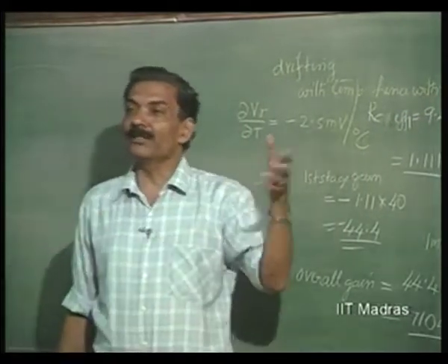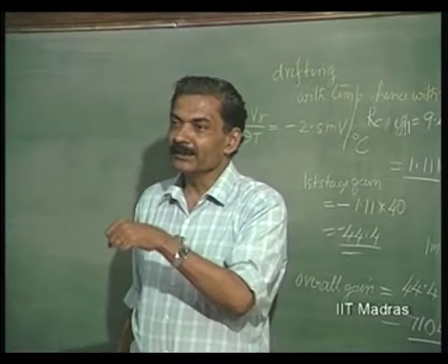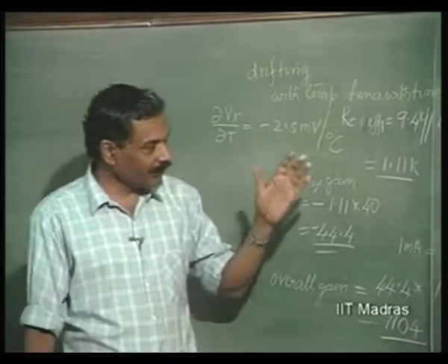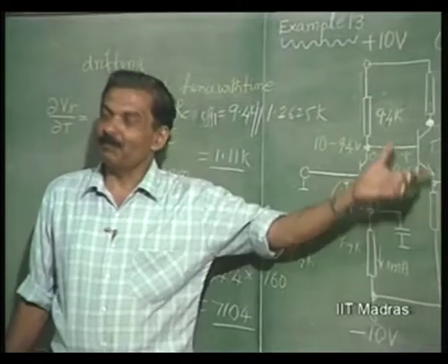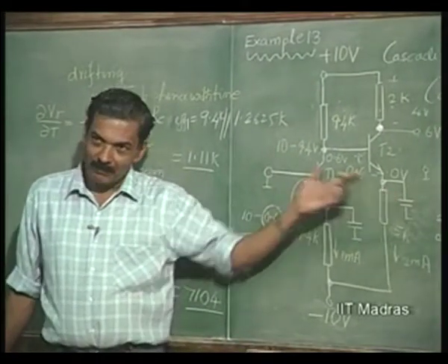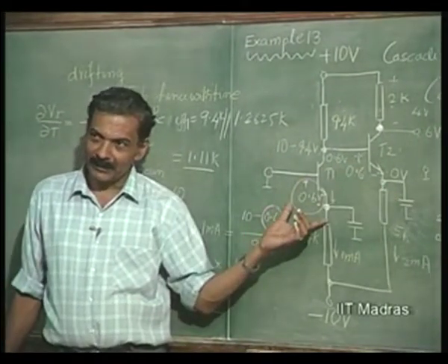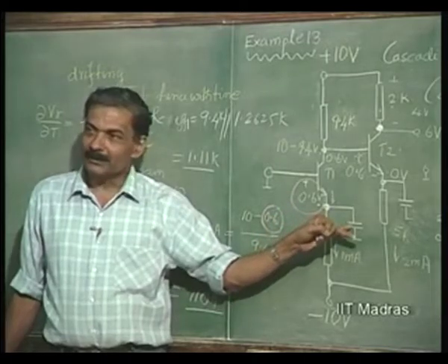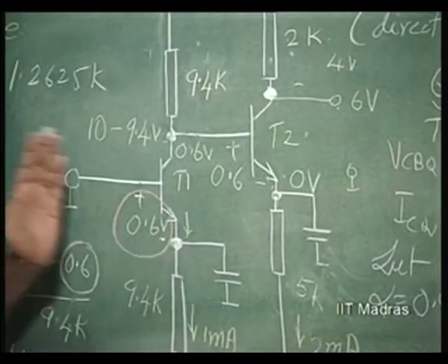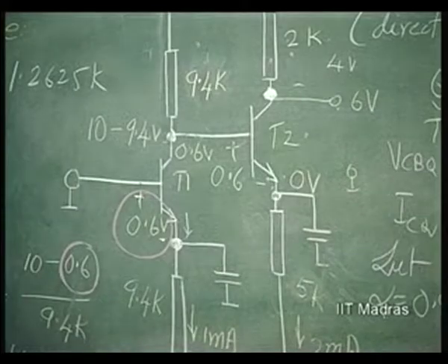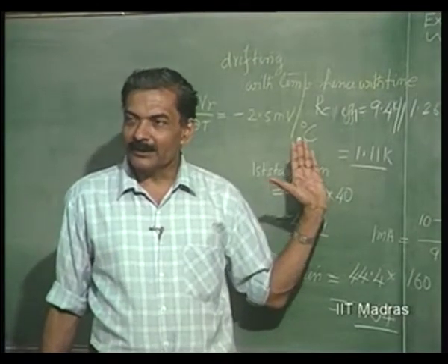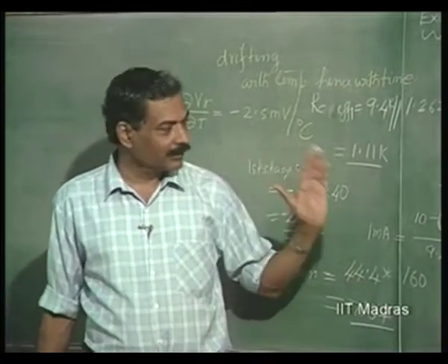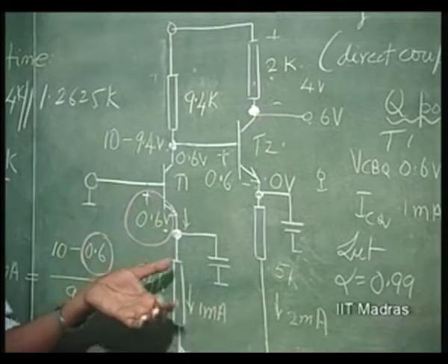That is almost equal to a DC signal. So, if you have a good DC amplifier, then you have a problem. But we do not have a good DC amplifier here, because this capacitor is going to limit the performance of this amplifier to a certain low frequency, on the lower side.